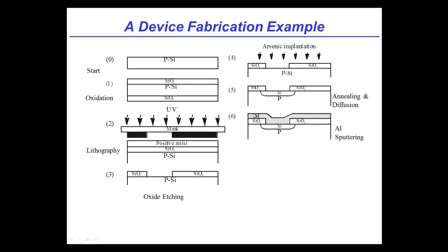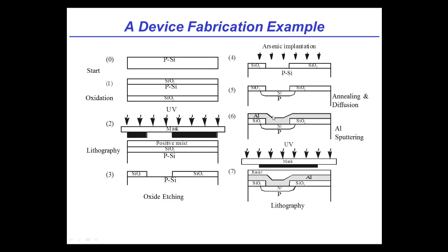So you'll notice it'll make a thin film, which will follow the topography of the underlying wafer, and wherever there's a step, of course, it's not going to go perfectly. It's just going to sort of follow it in a smooth, continuous way. Now, once we've got the aluminum there, we don't want aluminum everywhere. This isn't the inside of a potato chip bag. So what we're going to want to do is add patterns to the aluminum. We're going to want to remove aluminum where we don't want it.